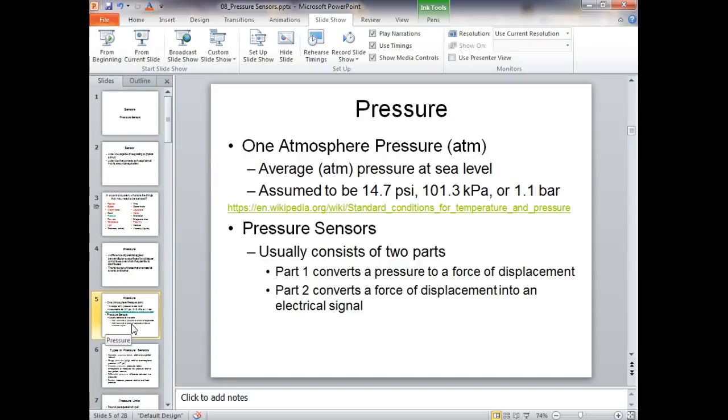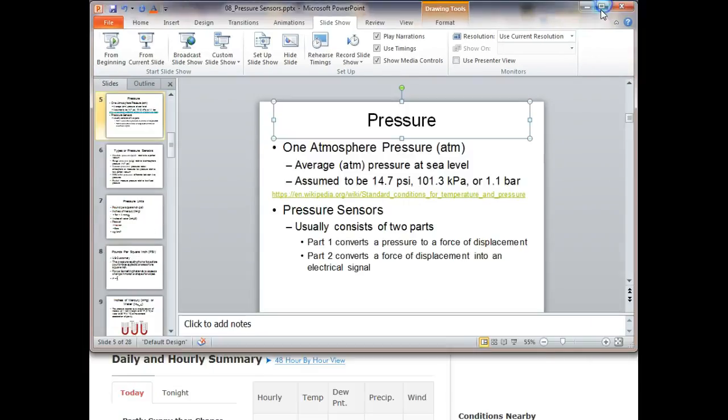You know that took motor controls. What's the advantage of a series motor? Nobody remembers. A series motor has very poor speed regulation, but it has extremely high torque characteristics. So we have to start that thing under load. There's probably already pressure in your tank, right? You got to put more pressure in there. So series motors have a really high starting torque. They have a real high run torque, but very poor speed regulation.